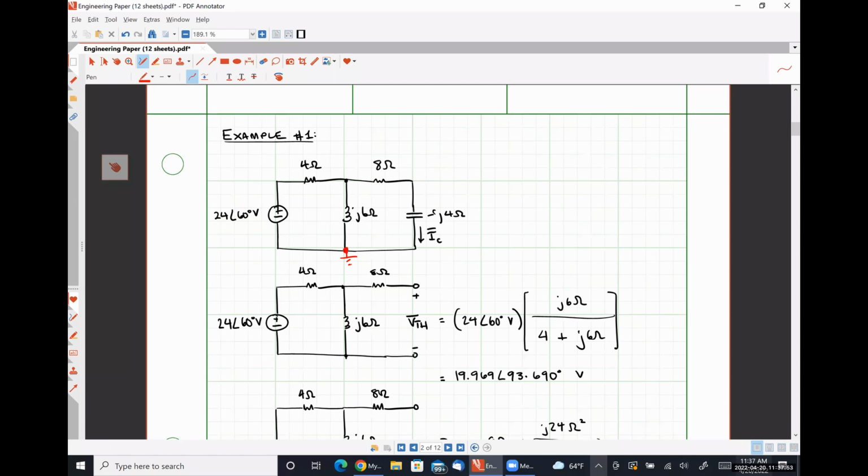But I would argue that's the least practical way to do it, although it absolutely works because it just relies fundamentally on KCL, KVL, and Ohm's law. It takes the most amount of time because we have to shrink everything down into 2 elements and then expand it back out to figure what we're looking for. So as an absolute last resort, that's fair game, but practically speaking, it's the longest possible method to solve this circuit.